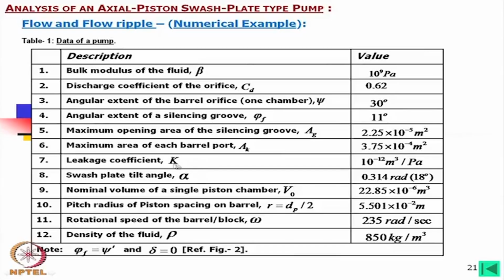That is why you will normally find that in pump, even in motor, as the silencing grooves are put in one direction only for the best performance, you will find the direction of rotation is mentioned there. So, we must maintain that direction. Now, leakage coefficient K, here we have not used the K theta, because K is constant for a pump. Irrespective of the stroke length, we have taken just single K.